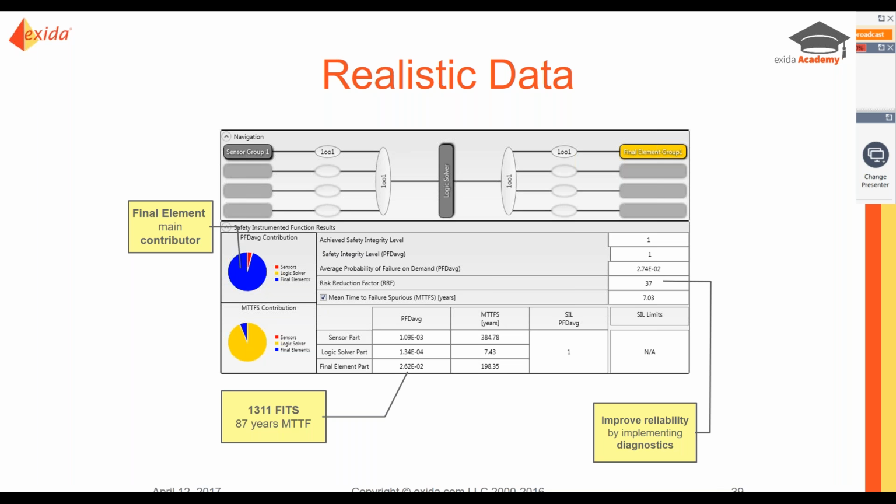So your valve won't have an accident in 87 years, or more likely you have 87 valves in your plant and you're going to have one trip a year. That seems much more realistic to me than having thousands upon thousands of years without having an issue.